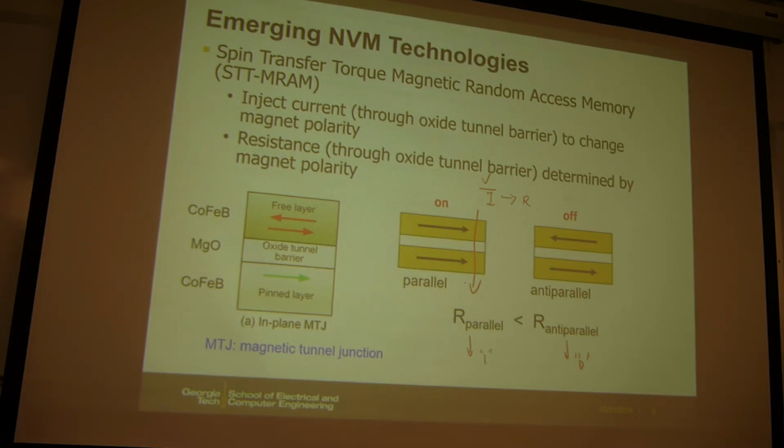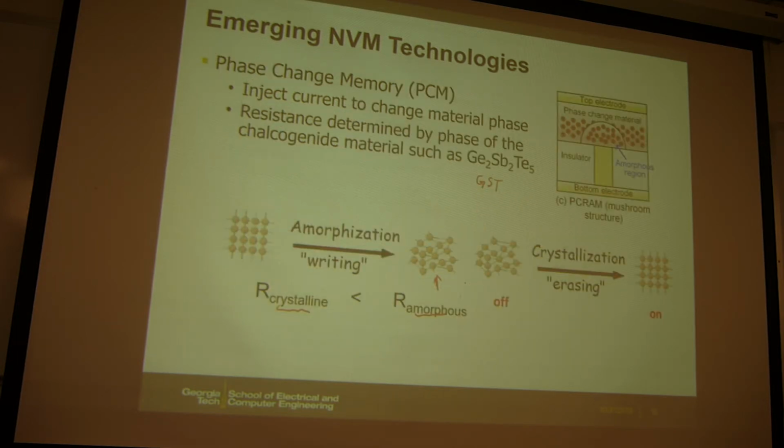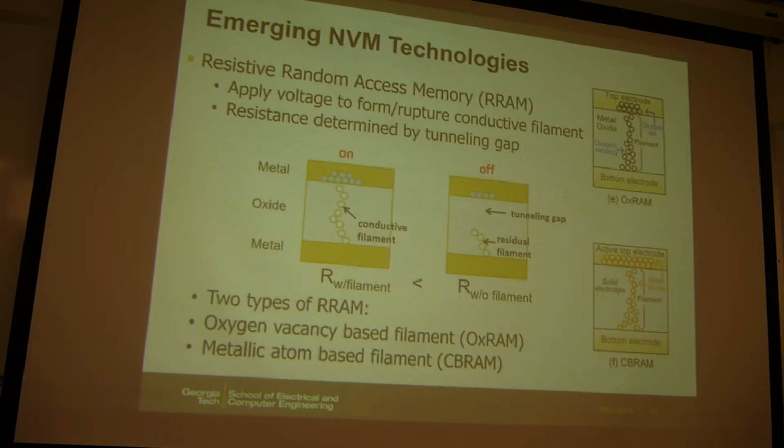So it's very hard to distinguish already. So you cannot have more levels. And like flash, you have many levels, right? Sure. So the phase change memory, yes, you can do multi-level. You can tune the resistance because the on-off ratio is kind of large, maybe 100 or 1000. So you can have many levels in between the very high and the very low states. I see. So yeah, this is doable.